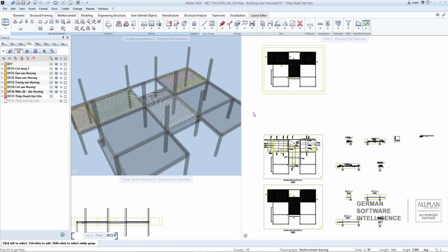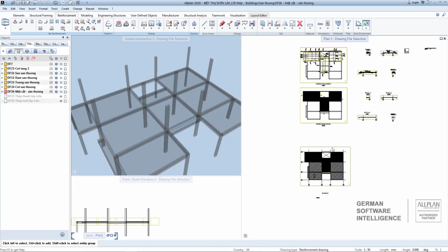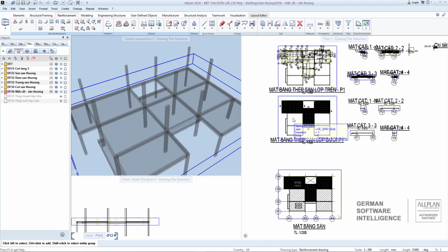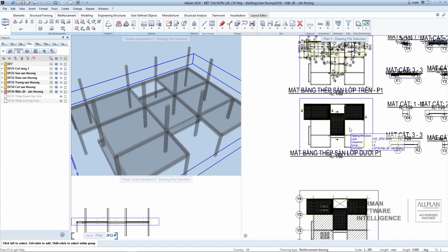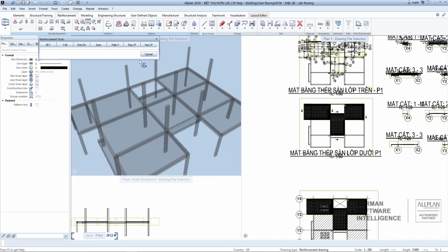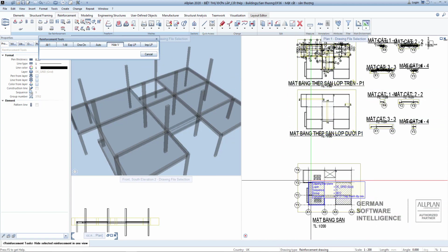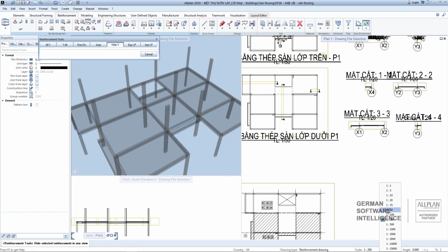Allplan also supports a rebar mesh drawing tool, and the operation is almost the same as regional bar placing in previous lessons. Before you begin drawing rebar for slab, you also determine the range to draw. Create sections and dimensions. The top layer rebar you hide by reinforcement tools. Select Hide Rebar in a specific view. Our area to draw is here.